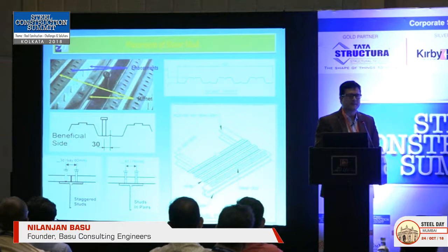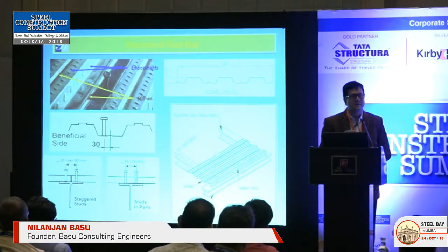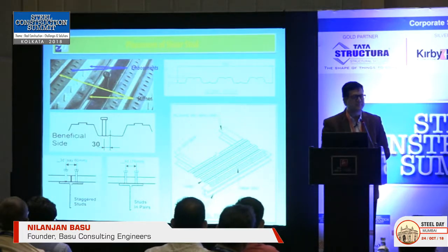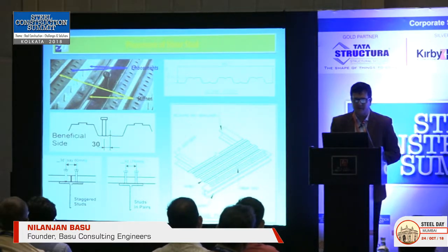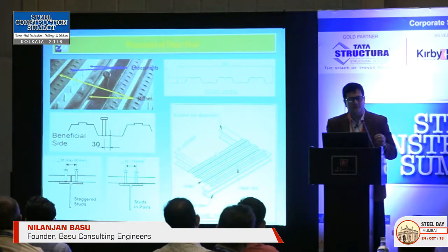Now, during construction, I've seen people just punching in the shear studs with the Nelson stud gun. It's not supposed to be done exactly like that. People have to specify where to punch in, the distance from the stiffener. The central zone, that is this part, is called the stiffener for the bending, for the metal deck.